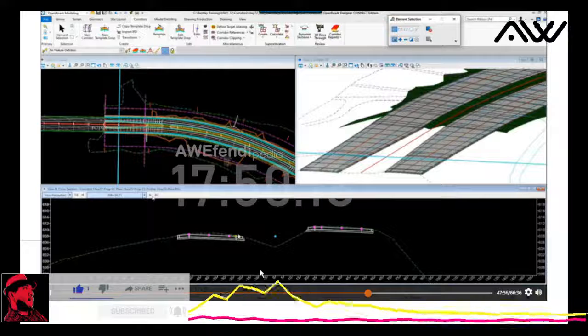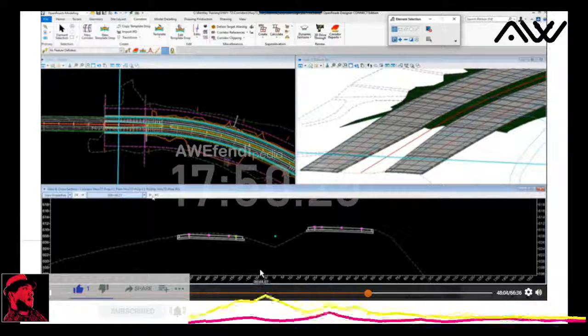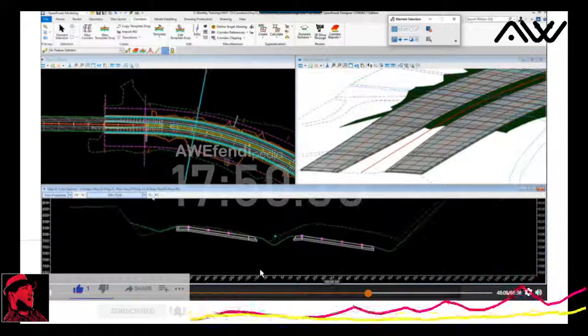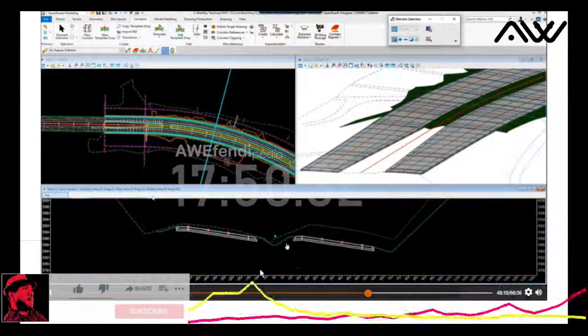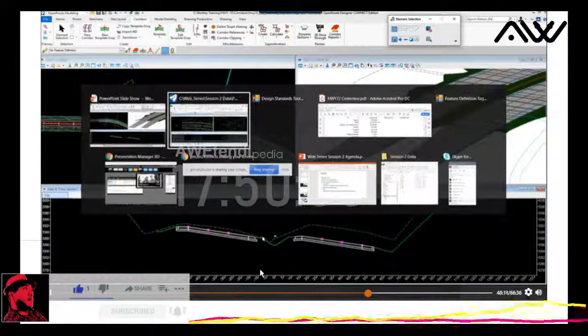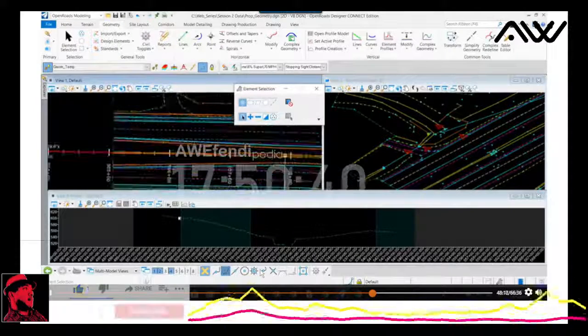You'll notice these hold elevation with one another. The eastbound will vary as we transition in the bifurcation and throughout the corridor, okay? So we need to create this elevation, the PGL, that holds to the inside edge of pavement within our westbound corridor. Now, how are we going to do that?